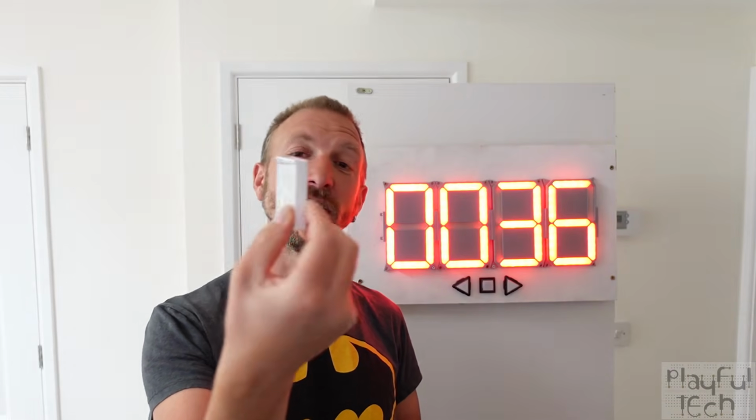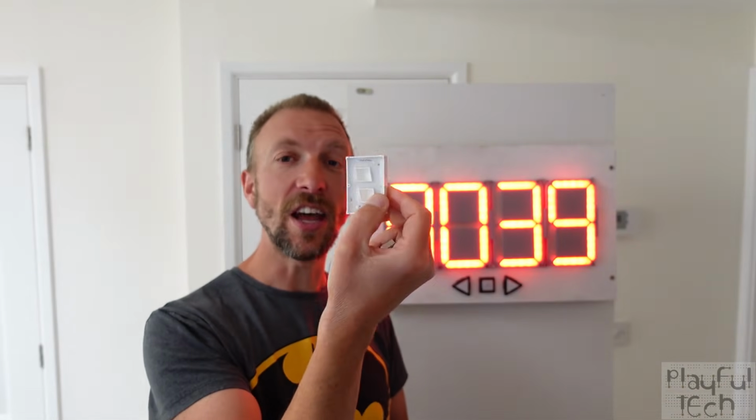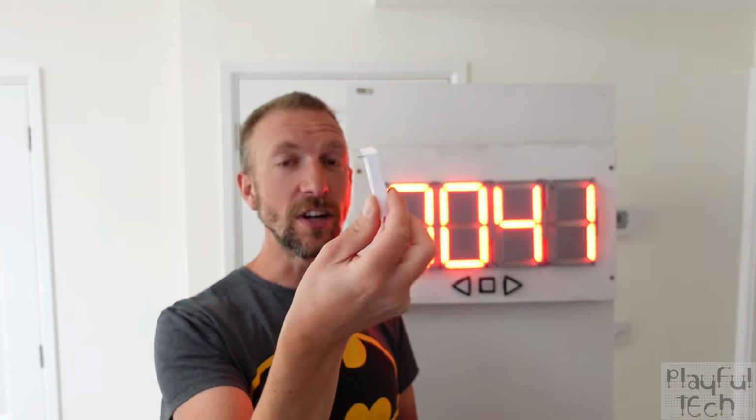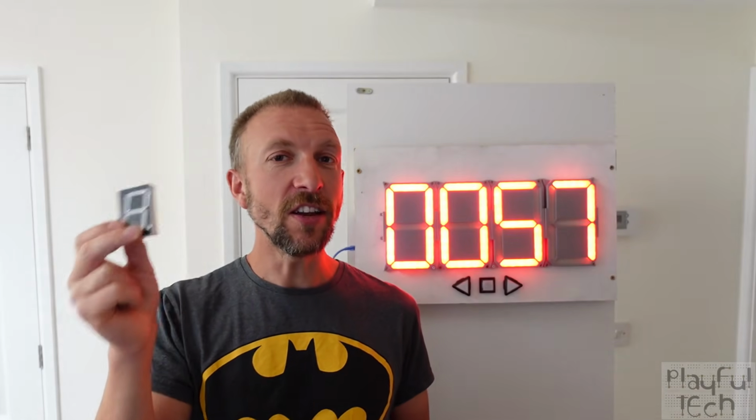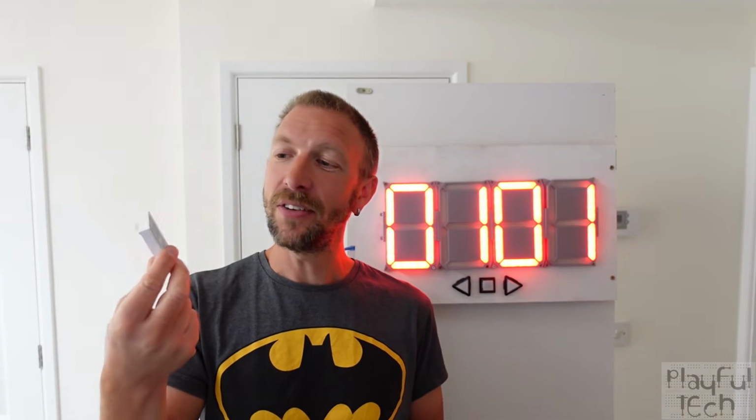Now, if you wanted to make a larger display, you could create one using individual 7-segment digits, such as this one. But this doesn't have any of the additional control circuitry, so you're going to have to combine it with some sort of driver, perhaps the powered transistor output from a shift register, and then you're going to have to worry about things like whether it's common anode or common cathode configuration, multiplexing, things like that. None of which are individually that complicated, but they're just a hassle. And these digits themselves are not that cheap.